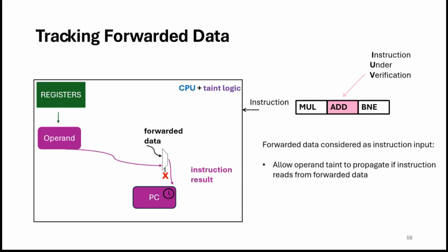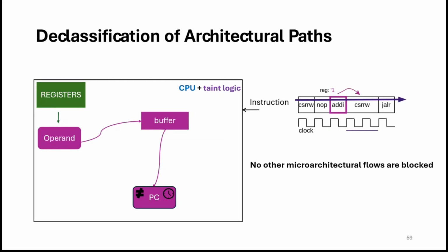So with the abstraction, you always verify more scenarios. In the end, the verification will also hold for the original design. That means in the case where everything points to forwarding, we let the taint from the register come in and thus also verify whether this instruction behaves differently in this case. By doing so, we make sure that we don't block any other flows that are unexpected.